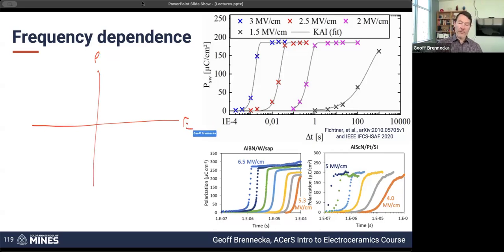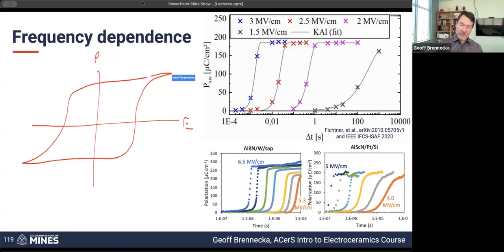So again, if you have a very low loss, sort of perfect material, the coercive field and remanent polarization should be very similar for different frequencies, but the coercive field will gradually get fatter and fatter as you go faster because it takes time for those domain walls to move through the sample. At some point, you're going to be measuring so fast that it can't keep up at all, or you could go so slowly that you won't see any difference at all in the measurement because you're not limited by the sample itself. Can you determine how much of the apparent polarization is due to loss?